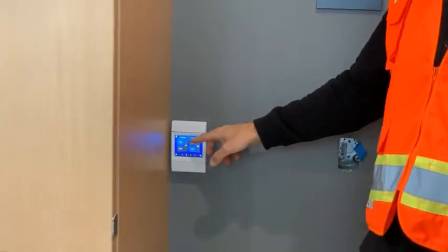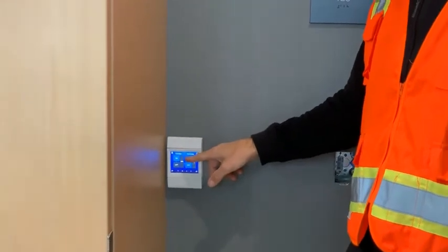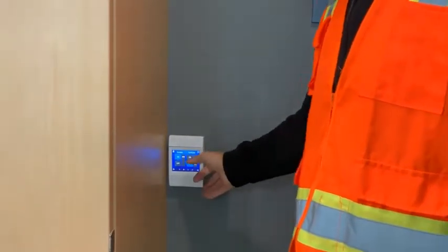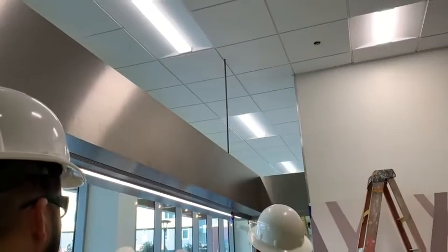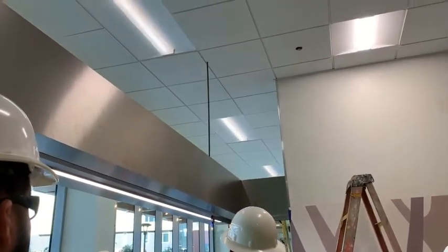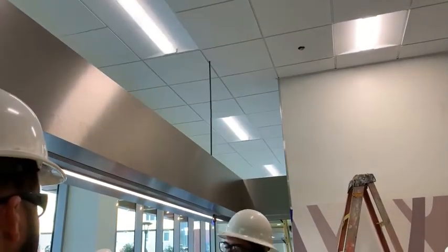So one difference you're going to kind of see is, and we'll look at it on the can. So if you watch the cans turn on and off, you're going to see a quick on and off. When you see the corridor 2x4s, you're going to see a slow fade. All right. The reason behind that is those are intelligent fixtures. Okay. They don't have a relay actually going to them telling them to turn off. They're inherently turning off in that system.